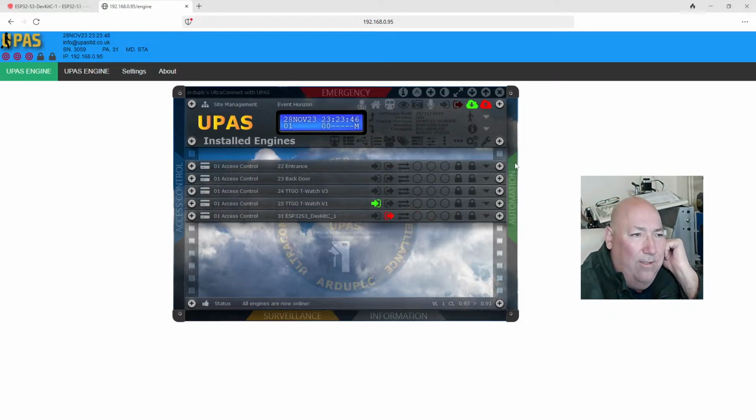As you can see, we've got outgoing and incoming packets from the cloud or wireless, and we've got red and green coming back off each of them. So they're all responding. You can see how it talks to that one, then it goes to the next one, next one, next one. Not only is it talking to see if it's there, it's asking it for its status. So it's reading all this back in one packet. It's pretty efficient. The packet's only 14 bytes long, 15 with a checksum.